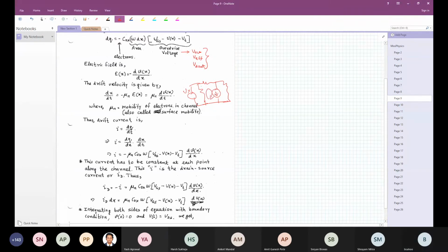No. Why not? Because by definition, this behaves like a current source for any voltage across it. So I cannot apply KVL across the current source. Similarly, a voltage source can sink any amount of current. Correct? Yes. So that is what we have to be careful of.